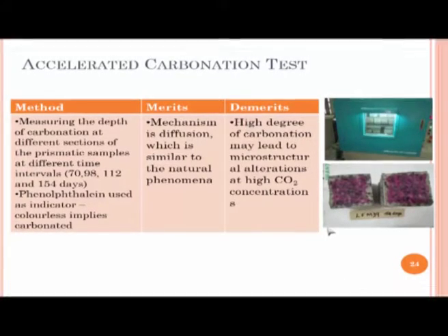What is the problem with carbonation? The carbonation problem only happens if the carbonation depth reaches the surface of your steel. When it reaches the surface of the steel, the pH around the steel becomes very low and the steel starts to corrode. That is why we want carbonation to be properly understood, to ensure that steel corrosion can be prevented in a carbon dioxide rich environment.